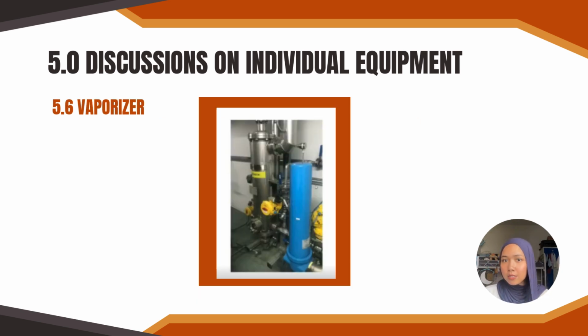Next is vaporizer. Ethylene oxide is stored as a pressurized liquid but must enter the chamber as a gas. A vaporizer uses hot water to rapidly heat the liquid ethylene oxide, converting it into gas before injection. This ensures effective penetration and successful sterilization.